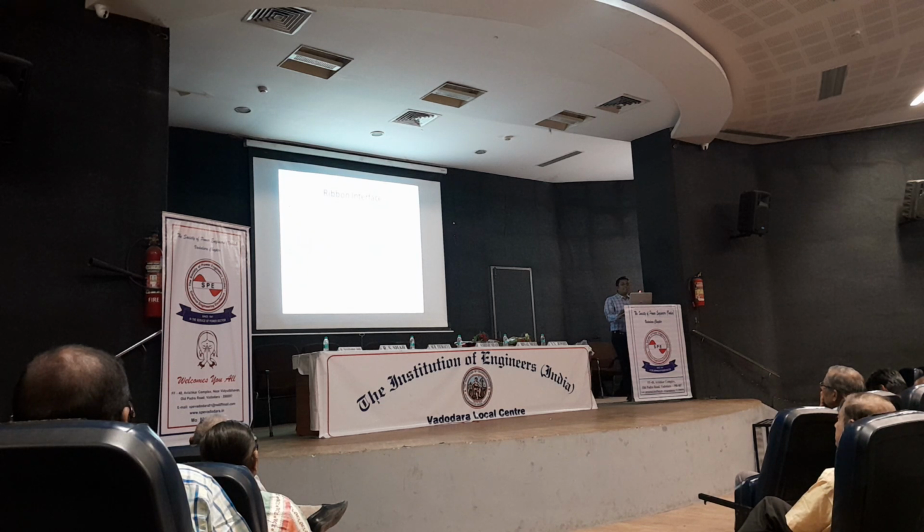So in edit mode, if you want to do the simulation, one tool, the solver, is given. Once your drawing is prepared, once your network is prepared, you can go to the tools and click on this green play button. Once you play it, your solution will be done and you have to analyze the data.